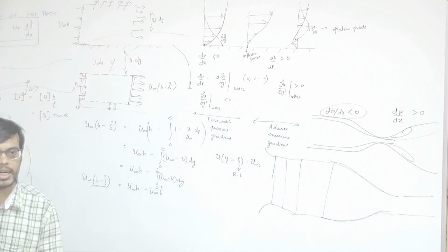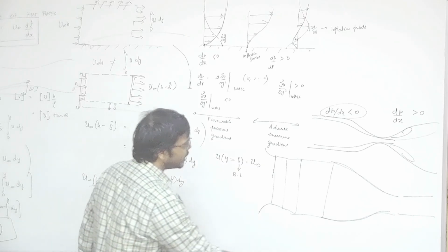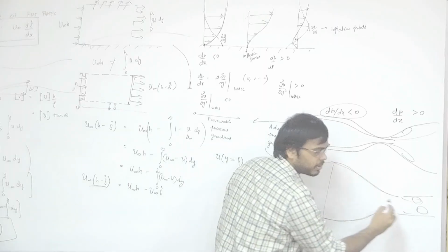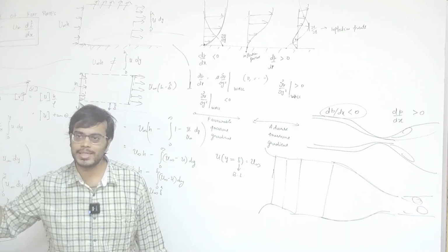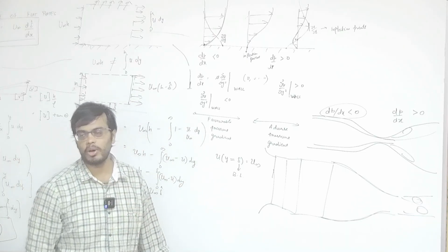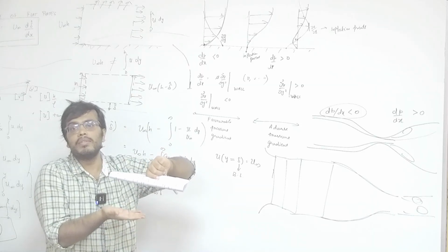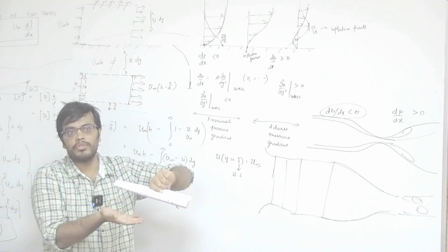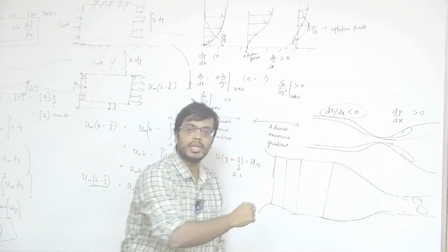So, it is trying to maintain the boundary layer. Why is it important? Because I do not want any recirculation zone in my test section. I want to model the flow as a uniform flow past some object. So, I want to maximize the area in the test section where the flow is uniform, and that is why we have a contraction zone in all wind tunnels.